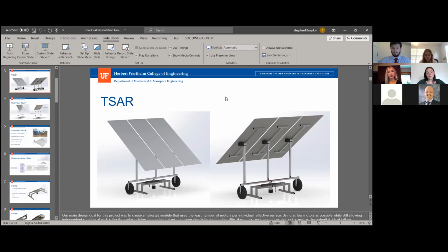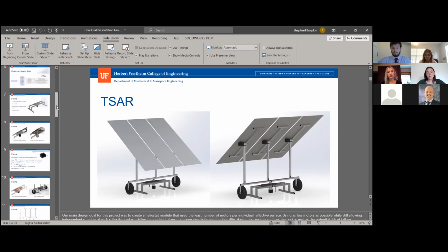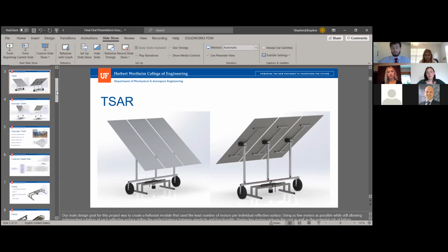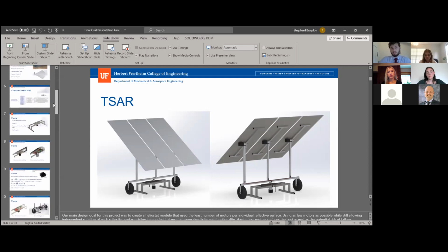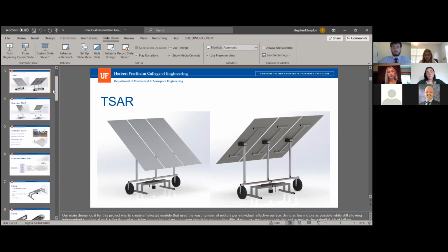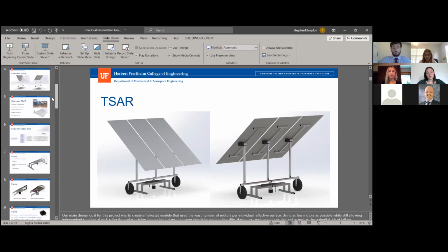It's a little hard to explain, but if you look at this as a 3-pronged fork, you grab the center tine and pull that backwards, you're putting a lot of torque on the shaft of that motor at the bottom. It's very low and the force is very high. So you're putting quite a bit of force with leverage on that shaft, out of the axis that it's intended to rotate.